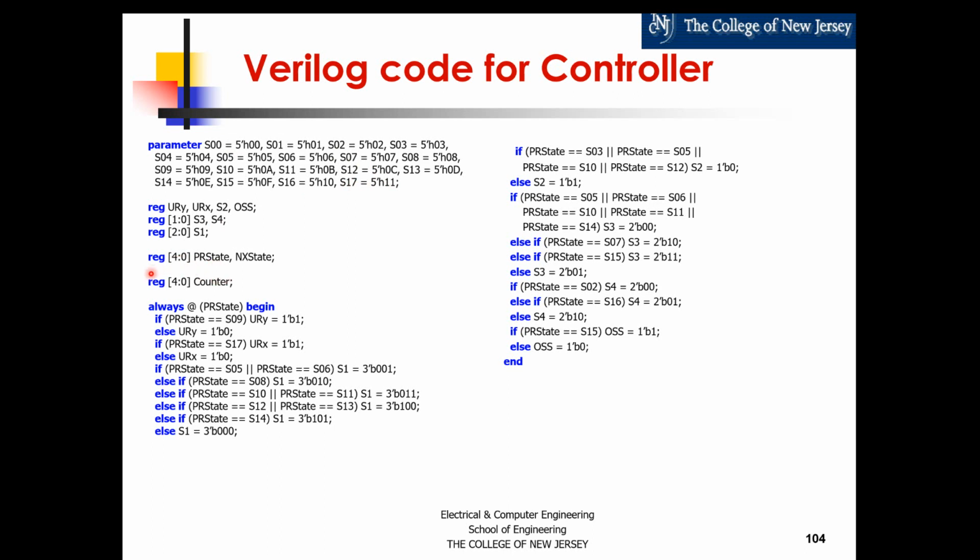Then I'm also going to need a 5-bit counter because I need to count. This is not part of the state machine, but it's part of the controller. I just need a dumb counter so that it counts 0 to 31. And when it rolls over, I know that I need to take the output of the top part of the algorithmic block diagram to do the bottom part.